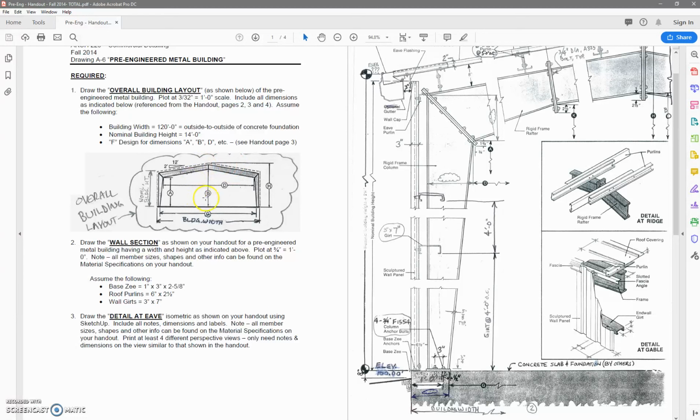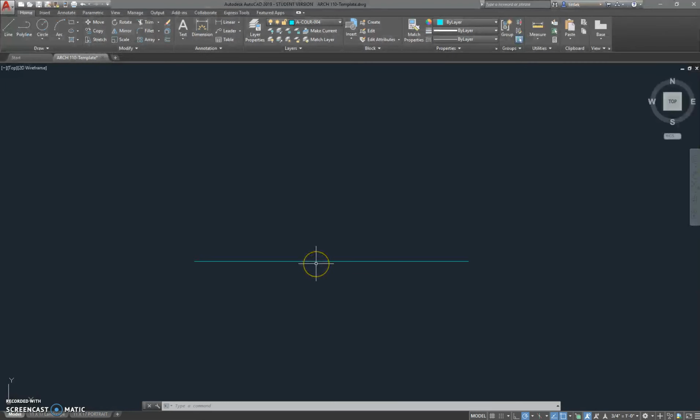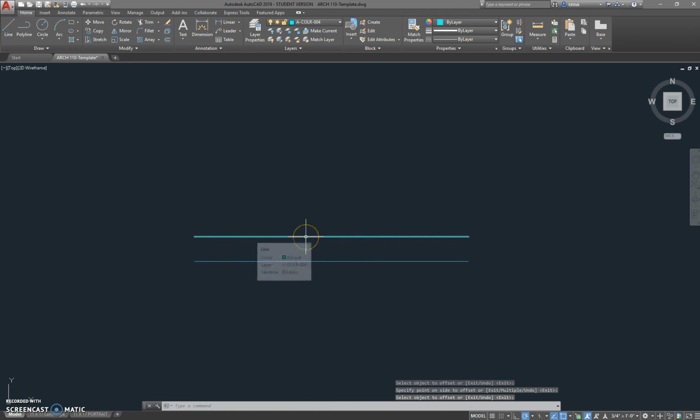And I do these in steps. I don't do all of these offsets all at once. I could also do K because that's a vertical offset as well. However, it starts to get confusing which line is which. So I'm going to start with A and H as an offset. A was 10 feet 9.5 inches, and I'm going to offset that. So that's A right there. It's a vertical dimension from the ground line.